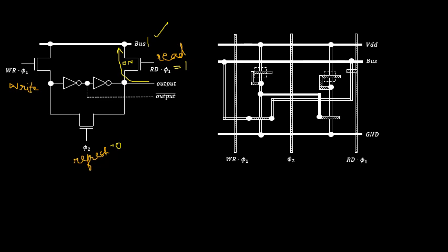So one thing we have to make sure in this particular concept is that I have to perform the read and write operation in such a way that when the write signal is asserted with the value of logical 1 state, this value is equal to logical 0. When this is 1, this value is equal to 0 state. So that is how WR, that is the write signal, as well as RD, the read signal, must be mutually exclusive in nature.